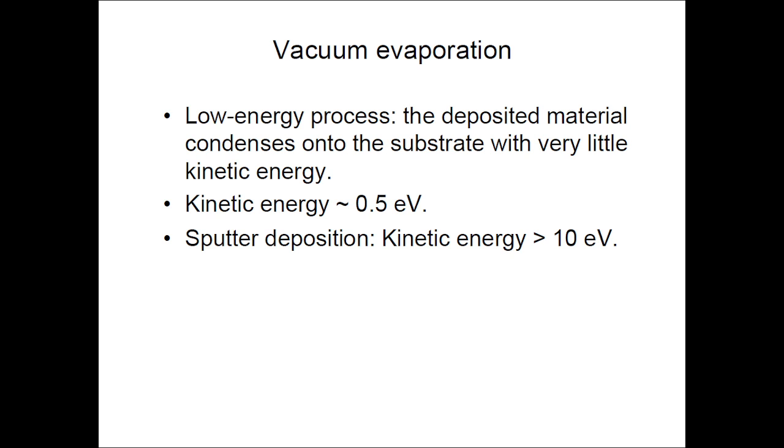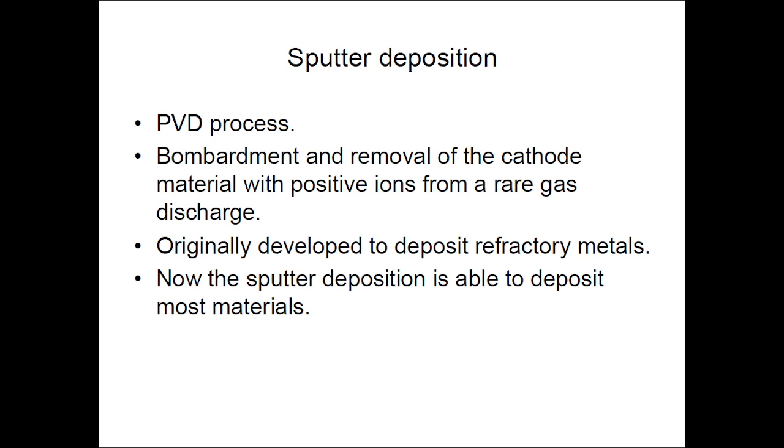If the atoms possess kinetic energy, there is always a probability that they can go over the substrate, so they may not adhere properly to the substrate. In that way, the vacuum evaporation technique has an advantage since the kinetic energy is less, so it can adhere to the substrate very easily.